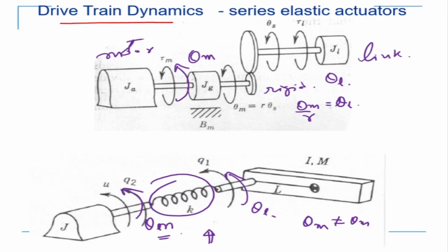Advantage of this: if I have a force or an impact load coming in there, part of the force is going to be absorbed in a deformation here, so it will not get transmitted onto the motor side. Okay, mainly in terms of safety. So today we talk of safe robotics, a lot of robots where these kinds of series elastic actuators are used.